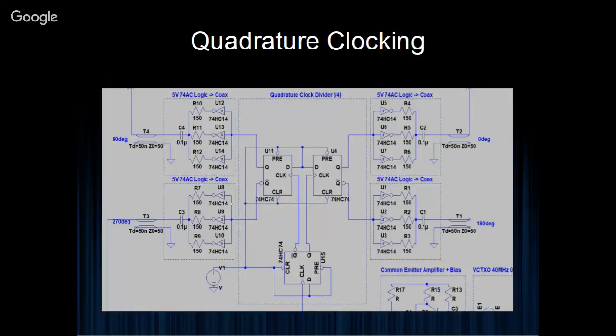The other thing to be concerned about there is the concept of fan out. When driving CMOS logic, CMOS logic is effectively FETs, and FETs are voltage-driven devices, with a capacitive gate on the FET input, which means that when you change the transition of a FET, you have to charge or discharge a capacitor, which is effectively a short circuit.